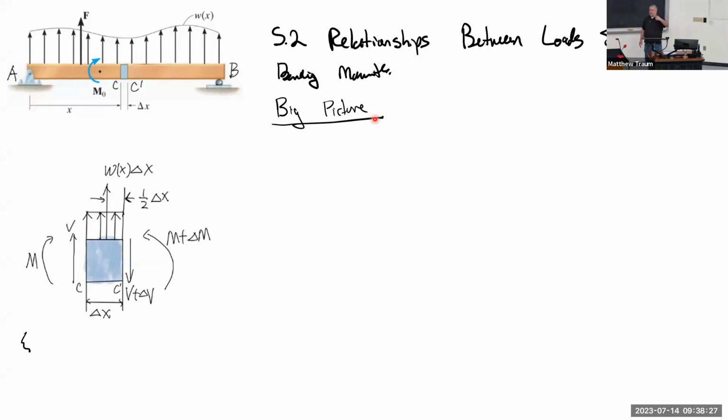So if you figure out the spot where the maximum bending moment and the maximum shear are, and you've determined that the member will not fail under that particular set of conditions, then it won't fail anywhere else, right? So we're basically not being lazy, but being efficient. We're trying to find the spot where the member is the weakest or where the chances of failure are the highest. Make sure that it doesn't fail at that spot, and then we know that it's good to go for the rest of the device or the rest of the member.